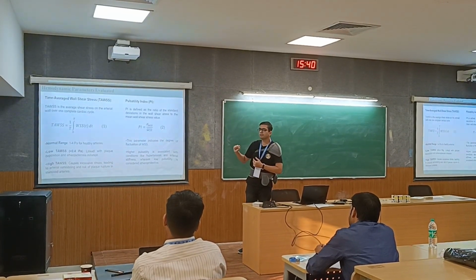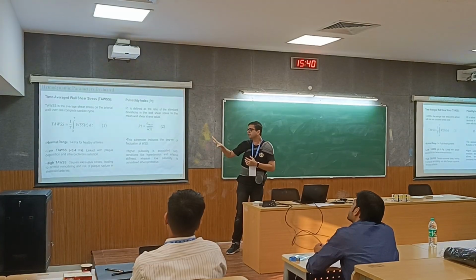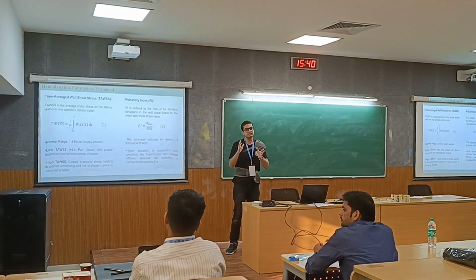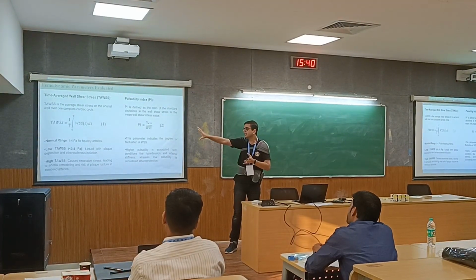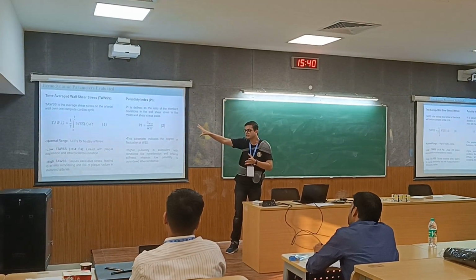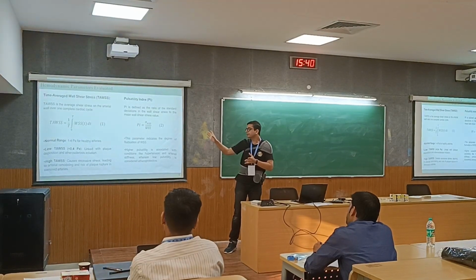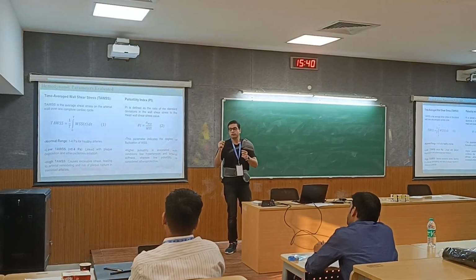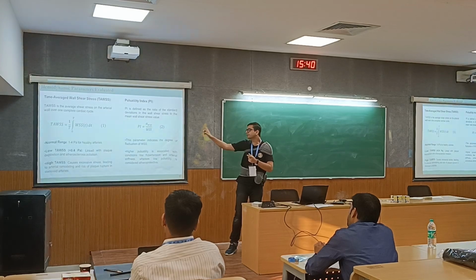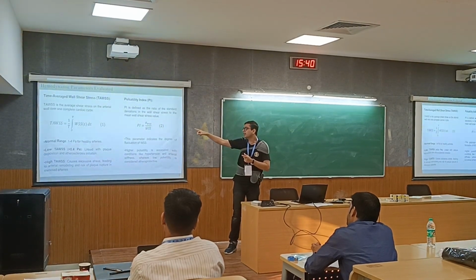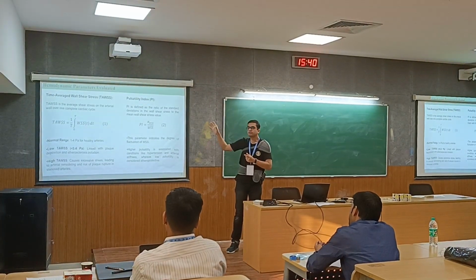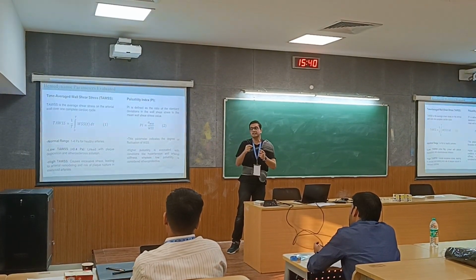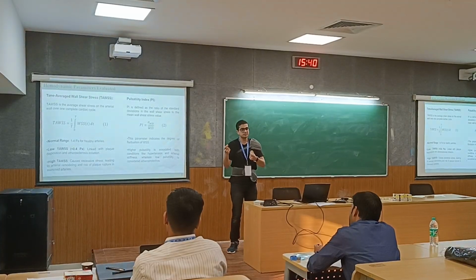The hemodynamic parameters primarily were two that we evaluated. We took the instantaneous wall shear stress data. We took the first order moment, wherein we did the time averaging of that. And second, we took the standard deviation from that mean, and then normalized it with respect to the mean, and we call this quantity the pulsatility index. This we defined so as to capture the fluctuation of the wall shear stress from the mean one.